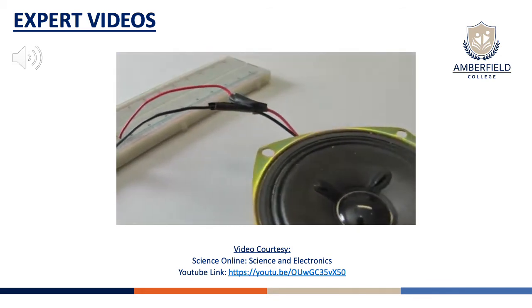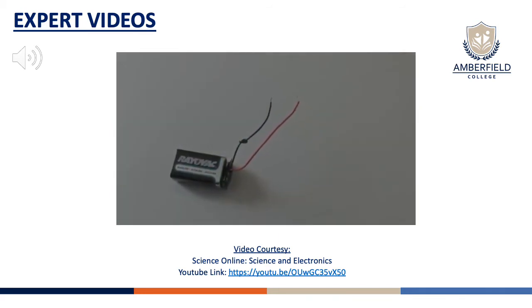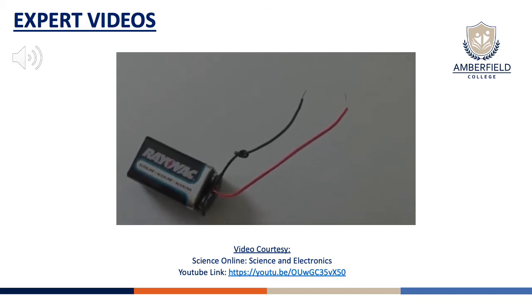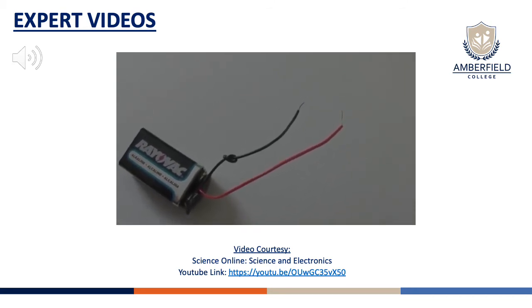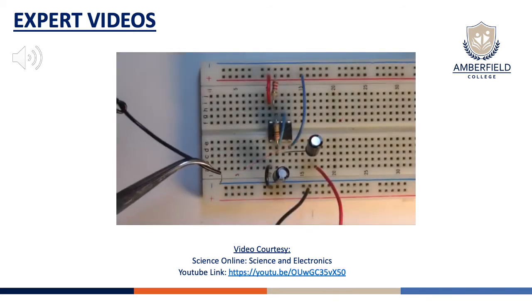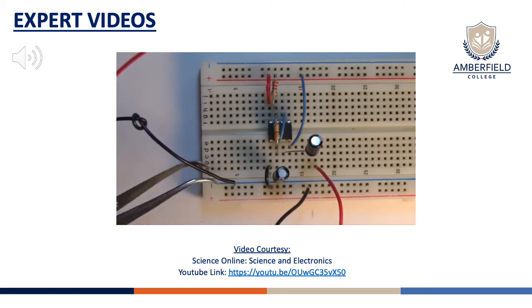We're ready to connect our power supply, a 9-volt battery. Do not use any power supply larger than a 9-volt low current battery like this one. Be careful you don't touch the 2 leads of this battery together. Even a small battery like this can cause burns when short-circuited. Connect the battery to the supply lines with correct polarity and you should have a tone.